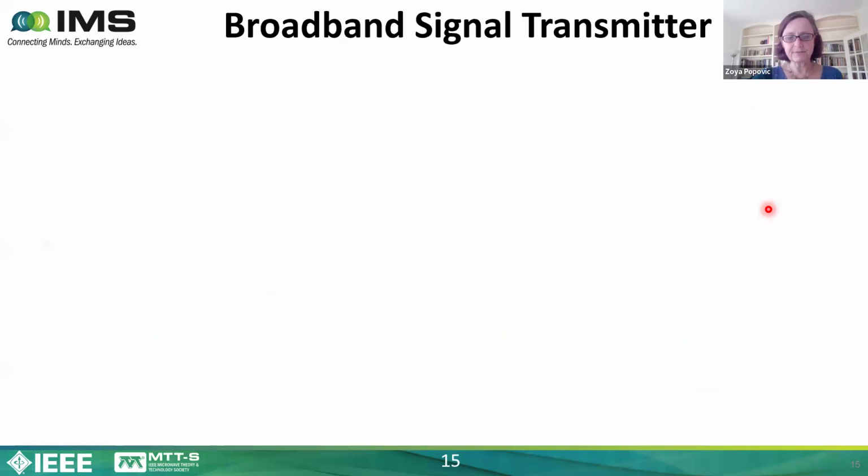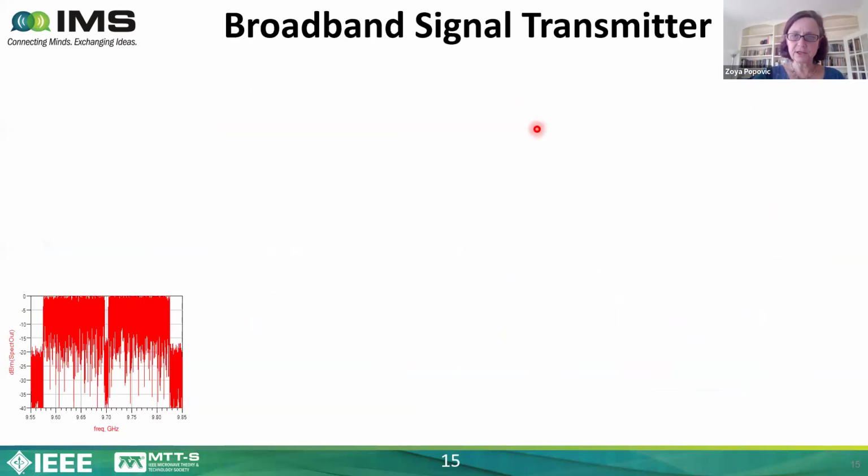So what can you get from this? Well, I'm going to talk about a broadband signal. There are 2 kinds of bandwidths. There's the RF bandwidth, which is the carrier bandwidth. So that, say, 2 to 18 gigahertz is a very broad bandwidth, right? 2 to 4 is quite broadband. It's an octave. And then there's the signal bandwidth or instantaneous bandwidth, and that's shown here.